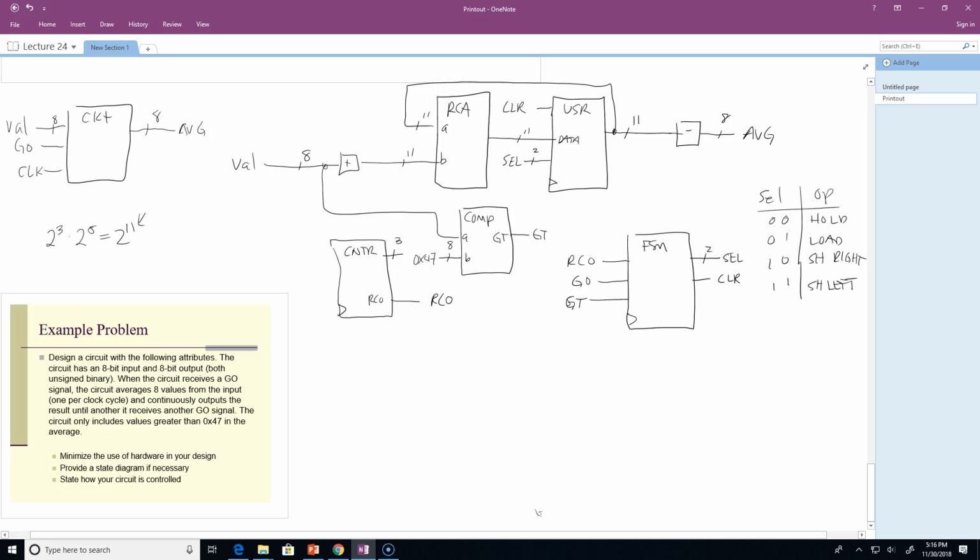And wow, am I done in this thing? Clear. And now I need to clear the counter to get it to non-state also. Okay, well, this is the other input. So I need to control whether I'm counting up on this thing. What I'm going to do is clear this. It's a 3-bit counter. It's going to generate the RCO when it hits 7, which means I'm kind of done with what I'm doing in the circuit. And so this is also a control input. And I believe at this point I think I've remembered everything. If not, I'll fill it in later.